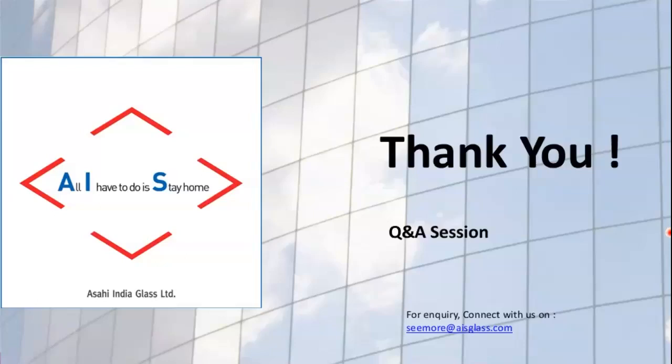Yeah, thanks, Naveen. One more question is from Mr. Chetan: for facade design, which method is considered, limit state method or working stress method? What does the code say about it? So it is purely a choice. You can use limit state method, you can use working stress method. Popularly in India, we are still using working stress method to do the facade design, but we can essentially use the limit state method also.